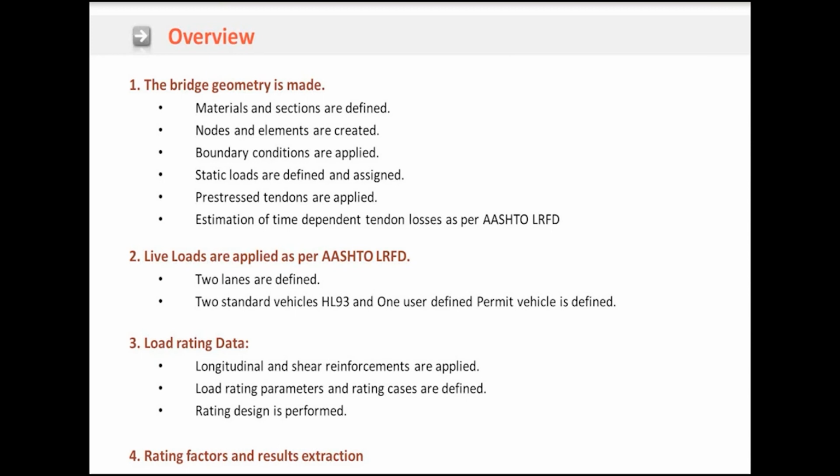Let's say modeling a certain type of permit vehicle with a certain tonnage, and then getting the result, taking it to the Excel, and then performing the load rating there with the spreadsheet that you created probably in your company or got it from the DOT. And then again, you have to do this iterative method to finally come up with the tonnage of the bridge or the capacity of that bridge.